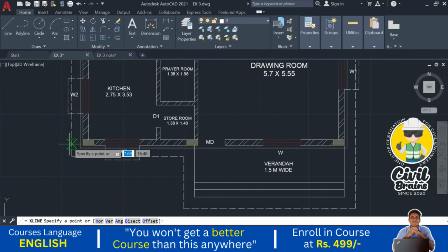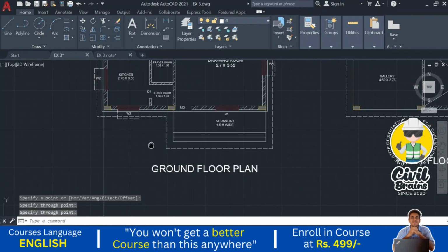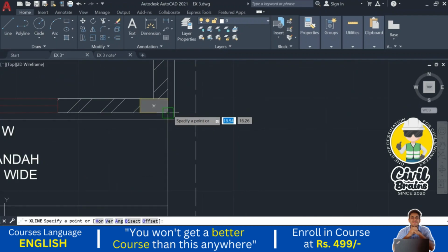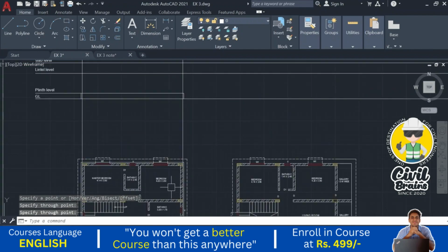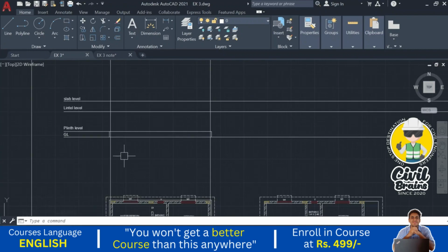Go to the corner of the wall, this one, I just projected, press enter. Again, I just go to the construction line, this corner of this wall. Again, I just click, projected. So from where it started, from the plinth and above till this slab.